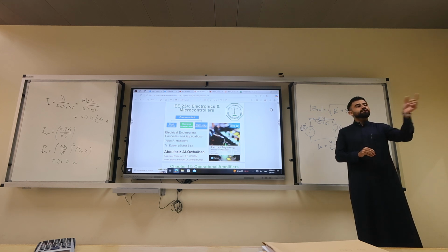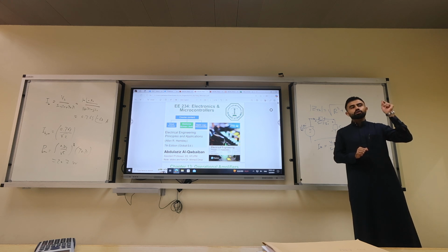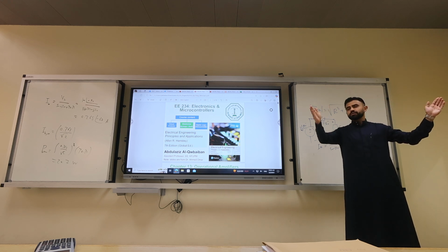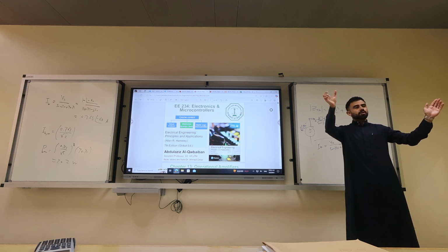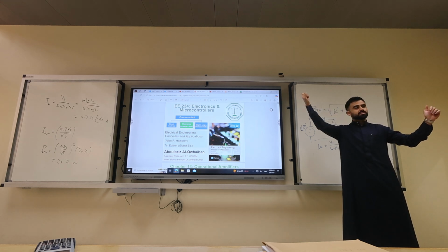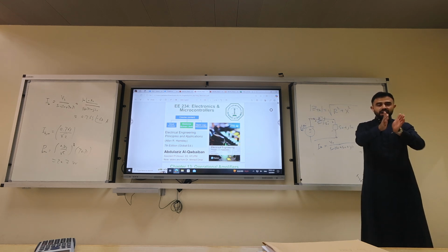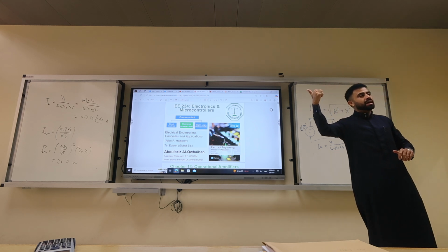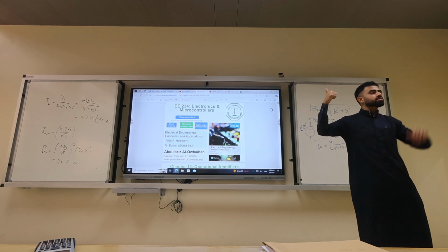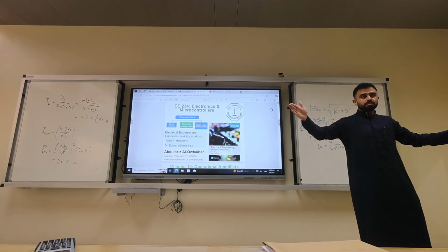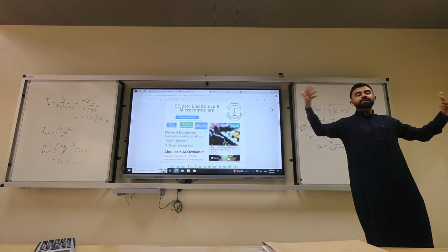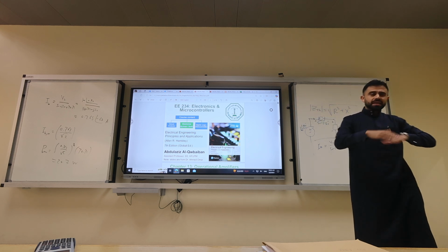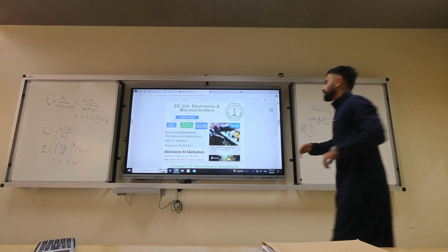Not much. Okay, if the difference in speed is 0.1, you are going 144.1 and the limit is 144. What's the difference? 0.1 times 100 times 1000 is what? 100. Is 100 enough to control compared to 1000? Of course the action will be more aggressive when you are going 145. The more the error gets larger, the more it's amplified. This is one of the basic applications of the operational amplifier.